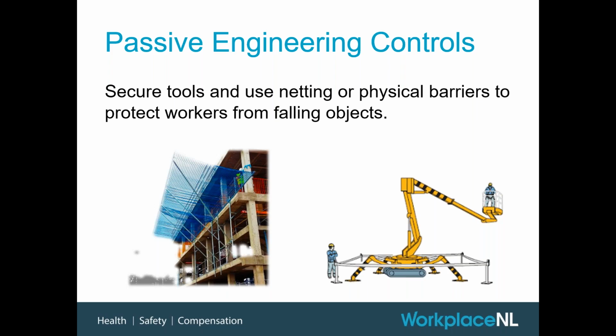And when you are using any type of lift or device, it's also not a bad idea to secure the area by setting up a work area using flagging or caution tape or something like that, certainly a little ways back from what you're doing, again, to protect people in the event that something is to fall.